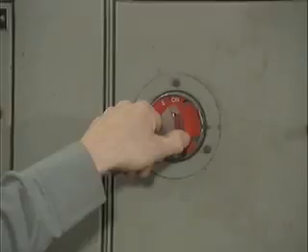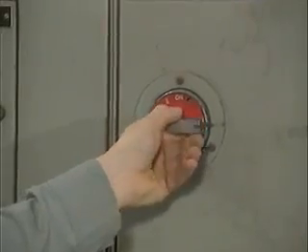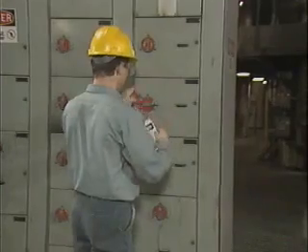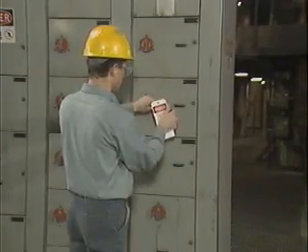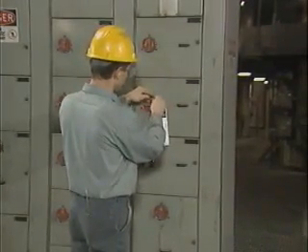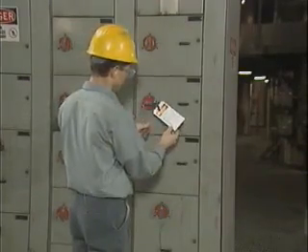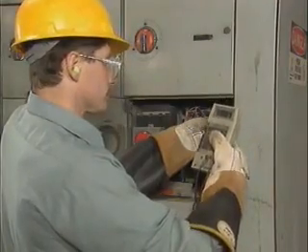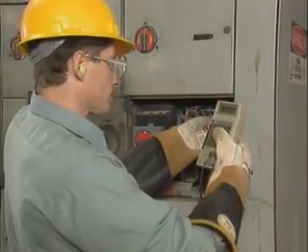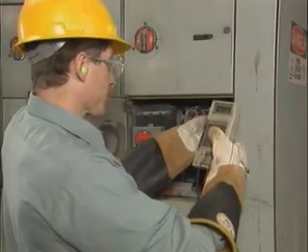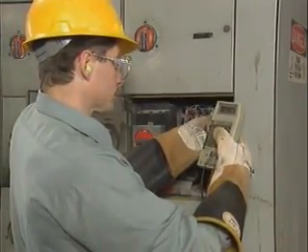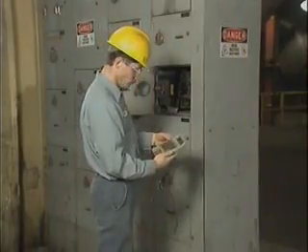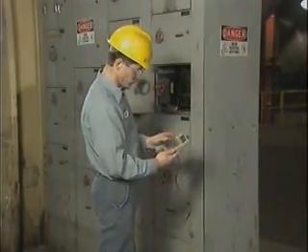For example, if there is a short in a controller, leaving the controller energized could damage the controller further. In addition, megometers and multimeters, which are the test instruments typically used to test for grounds and shorts, can be damaged or destroyed if they're used on energized equipment. After the controller has been de-energized, locked, and tagged according to your company's procedures, it should be tested to make sure that it is de-energized. You can use a voltage tester to test all three phases, phase to phase and phase to ground. After you're sure that the controller is de-energized, you can proceed with testing.